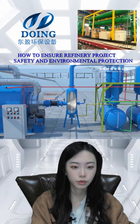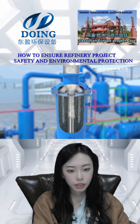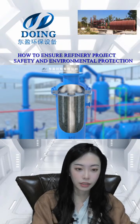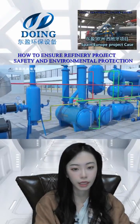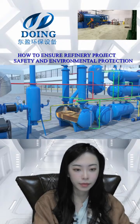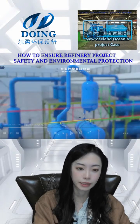First, it will come to the buffer tank, which is the first one, the vertical condensers, because in the first coil the oil is relatively heavier and sticky. So in this vertical design, the oil continuously flows down the wall to prevent blockage. Each condenser is a 108 millimeter pipe. The pipe is surrounded by circulating water, and the heavy oil will temporarily stay here.